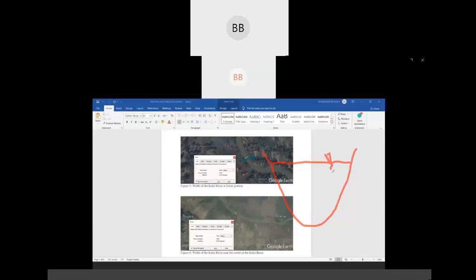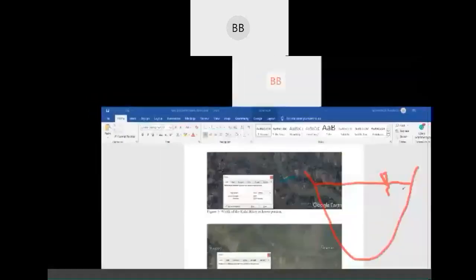So when you have a section like this, which is irregular in shape, now the question is where you are going to measure velocity. Where, what will be the velocity of flow in that particular channel section. See, we all know when you consider the bottom of the channel, suppose this is your boundary of the channel.